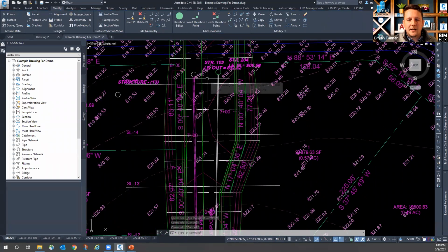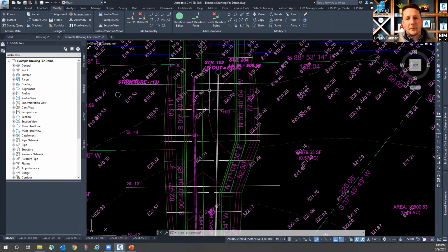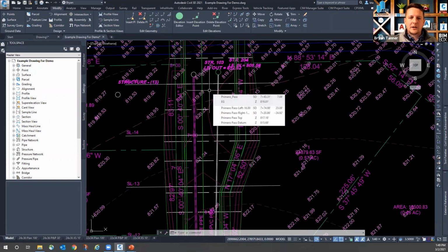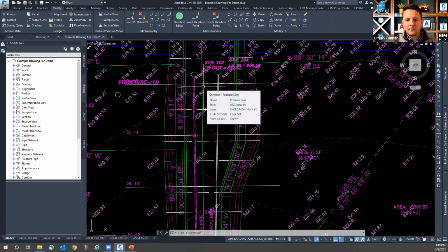If you do make any modifications to your parts list after that same pipe or structure type has been added into your drawing, we have to go back and swap the part, even if it's the exact same type of part, the exact same material and diameter. We do need to swap those parts to make sure that there's consistency in our naming, consistency in all of the pipes and structures that are included in the set of plans.